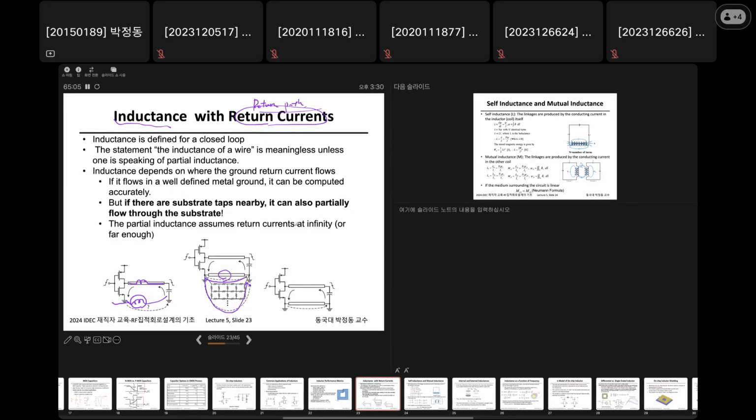In our lab, we always make a solid routing return path by placing ground metal all over the place, right? Since inductance is inversely proportional to width, if you make this width very wide, then the inductance will be negligible. So we can neglect this. Okay, so this is very solid. That's our design strategy.